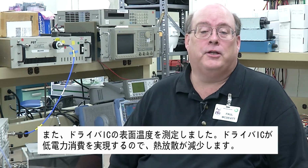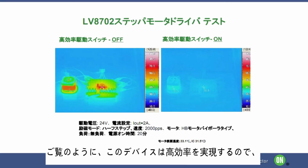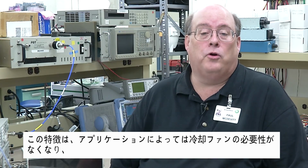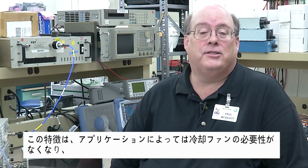We also tested the surface temperature of the driver IC. Since our driver IC realizes low power consumption, it reduces heat generation. As you can see in these images, due to the increased efficiency, the surface temperature of the driver IC and the motor are decreased by up to 46 degrees C and 28 degrees C respectively with the efficiency feature activated. This feature has the potential to overcome the need for cooling fans in some applications, along with the corresponding space and cost savings and enhanced system reliability that the IC provides.